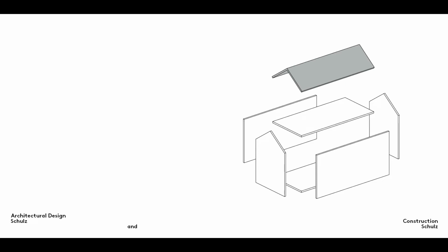Remember that concrete is cast in its liquid state, and for an angled surface, it would therefore be necessary to take measures to stop the concrete simply running away. As a result, it's much more common for pitched roofs to be made by the addition of linear elements. This is generally done with wooden beams or steel girders. Flat elements are then laid over these beams or girders to form a roof structure known as a roof truss.